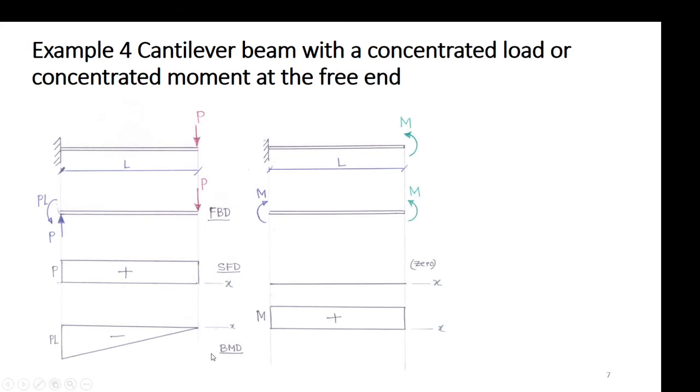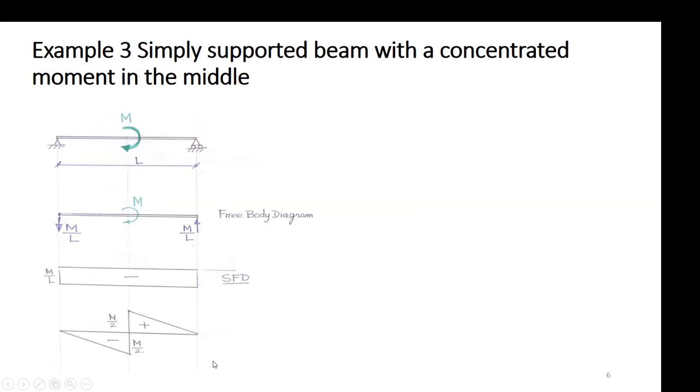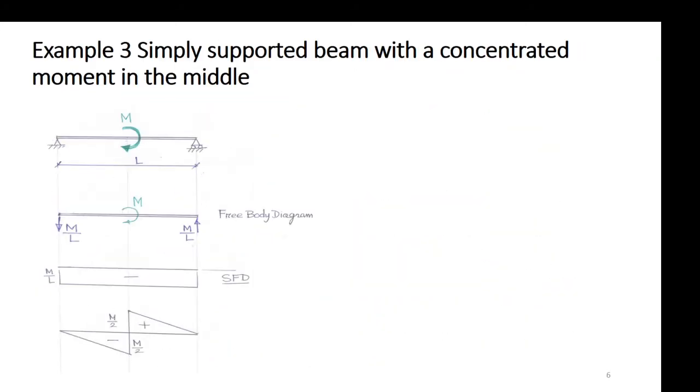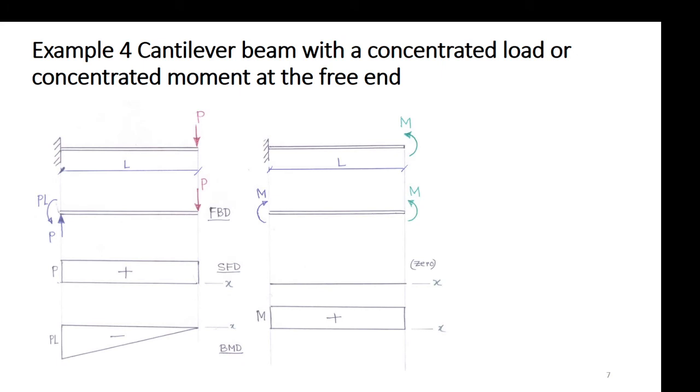Now I can add one more example quickly. If you have understood the simply supported beam very well, why not consider a cantilever beam and explore how the bending moment and shear force diagrams will look? Take an example of a cantilever beam with a tip vertical downward force P here. If that is so, then you have a P force here.